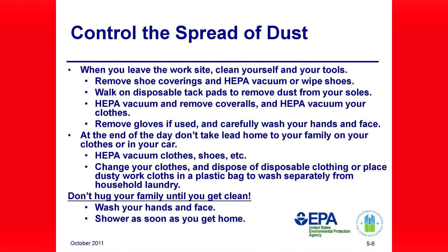Every time you leave containment, HEPA vacuum and remove your disposable coveralls and disposable shoe covers. Clean and/or vacuum your shoes and wash your hands and face. At the end of the day, change your clothes and wash yourself to reduce the risk of contaminating your car and taking lead dust home to your family.